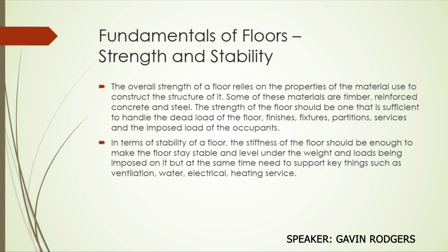Under strength and stability, the overall strength of a floor relies on the properties of the material used to construct the structure of it. Some of these materials are timber, reinforced concrete, and steel. The strength of the floor should be sufficient to handle the dead load of the floor, finishes, fixtures, partitions, services, and the imposed load of the occupants.